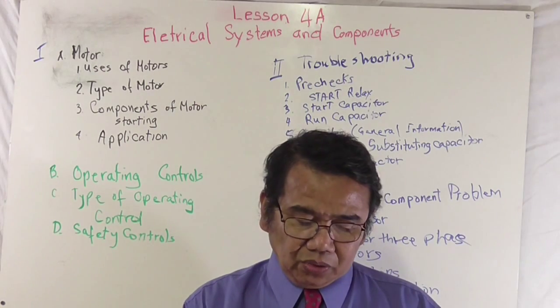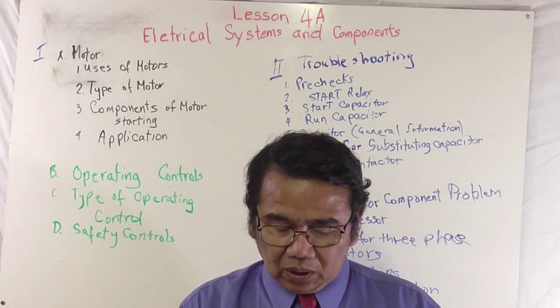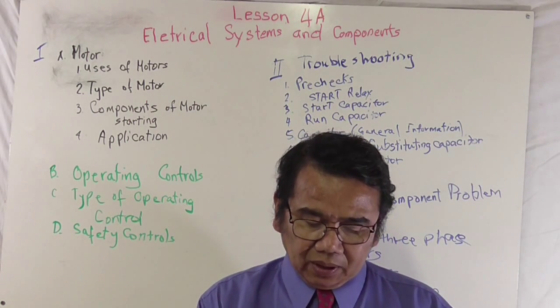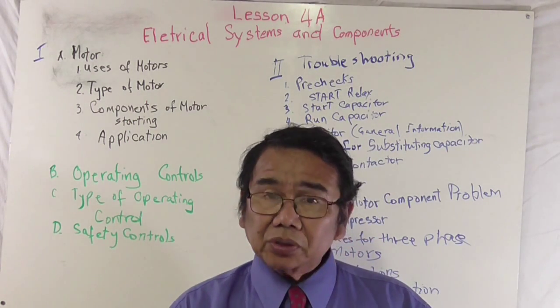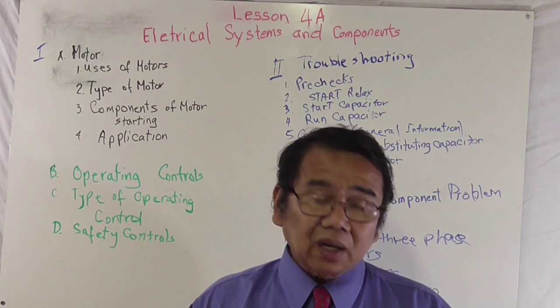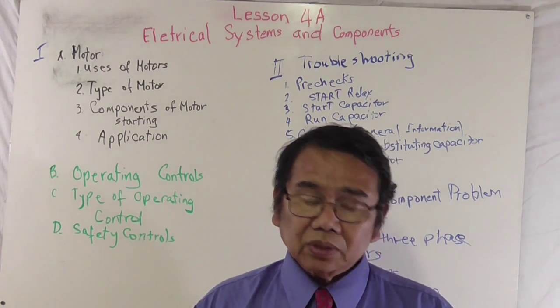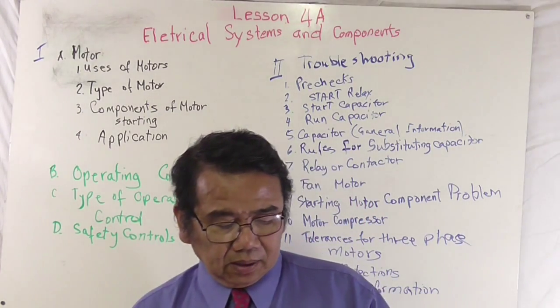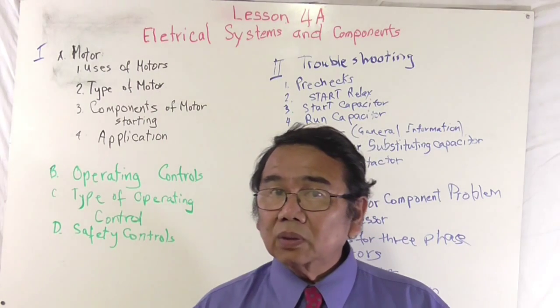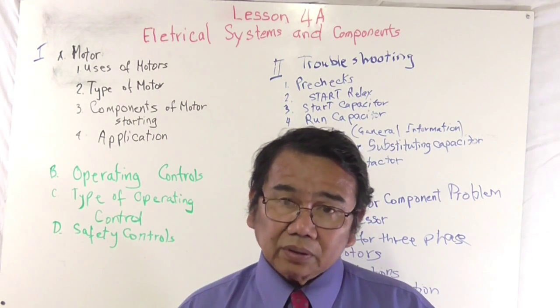On some AC units with a 1.5 pole contactor, the run capacitor will have a resistor to meter a small amount of current to the compressor to act like a crankcase heater. A dual run capacitor has 3 terminals.